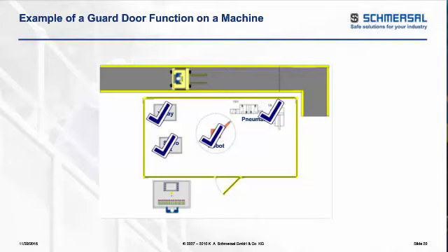So on top of its safety circuit, we're going to add the additional contactor or contactors to break the main power that's feeding that X-ray if that guard door is ever open, to ensure that even if a failure in the existing safety circuit occurs, because we don't have any documentation to back up that that X-ray controller meets any safety levels, we're putting that extra in there to make sure it meets a level that we accept as a control category 3, performance level D, to always ensure that's shut down so nobody's exposed at that particular time.